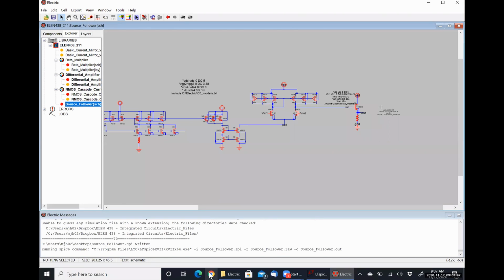So what I would do is, your servos should have three terminals, right? One for positive power, another for ground or the negative power supply, and the other for the information signal that tells it how fast to turn in one direction or the other. So I would run the servos' power off of an external supply.